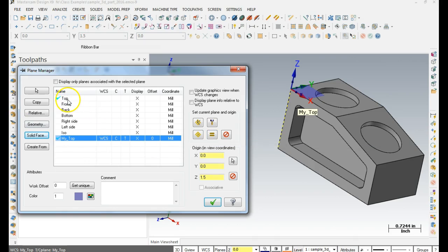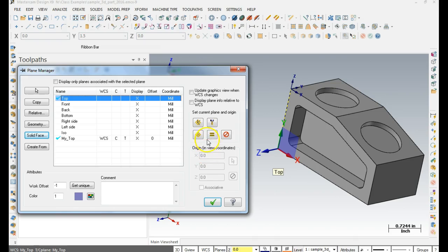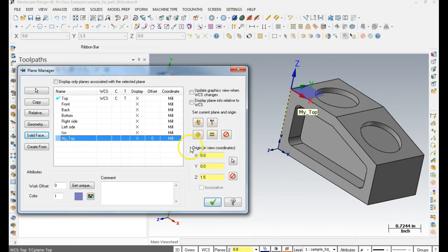Okay? And it'll bring everything in. For example, before I leave, if I go to top and I hit equal, it moves everything there. But if I want to come back to here, I click here and hit equal, it brings everything there. All right, that's very, very important. Because if not, it'll load the toolpath in the wrong plane, and you'll get all kinds of weird errors.